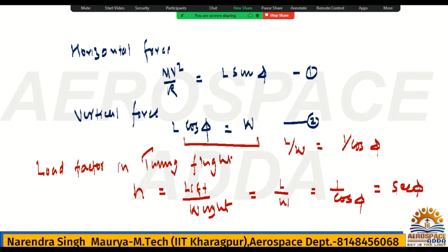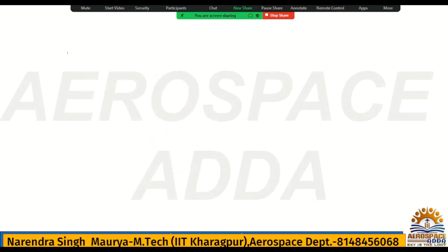It is clear? So I can say the load factor for the turning flight is 1 upon cos phi, which is nothing but sec phi.